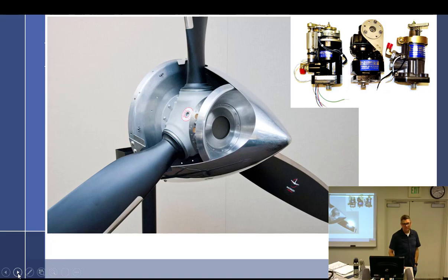Manual control mode, where you can have a lever? Kind of. Depends on what you're trying to control. The RPM? Yes, absolutely the RPM, but not the angles. Gotcha. All right, so where am I at? Pilot sets the RPM, and blade angle changes to hold the RPM. So I can't control what the blade angles are doing. I can control what the RPM is.